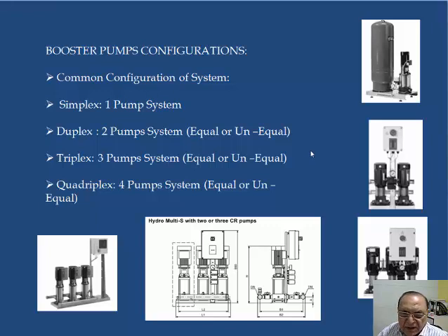The multi-pump systems are required generally when we have a larger flow and varying demand, and that is how we can size it, whether equal or non-equal. Like when we say triplex, we can have 3 pumps of 33, 33, 33. Okay, and 25, 25 with one standby 25. Likewise, that is the designer's consideration he has to follow.